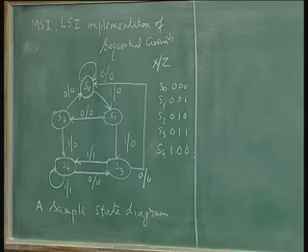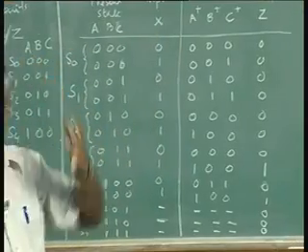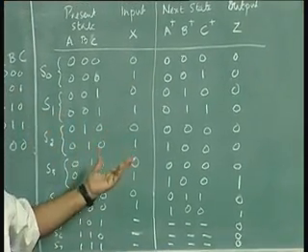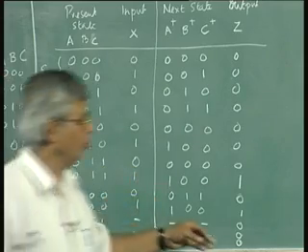So, now I use a ROM instead of a mux, a PROM. That is even easier. There are 4 outputs which are DA, DB, DC and Z. How many inputs? 4 inputs. This can be considered as a truth table for a PROM implementation.